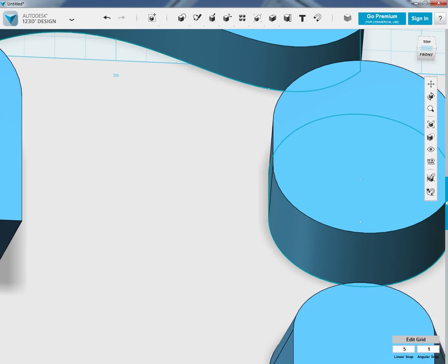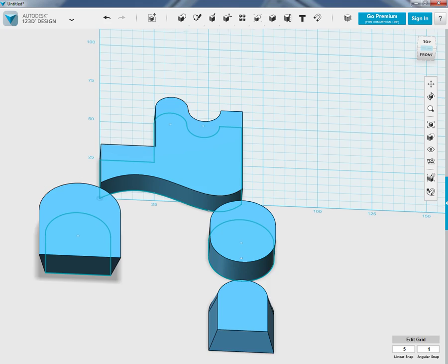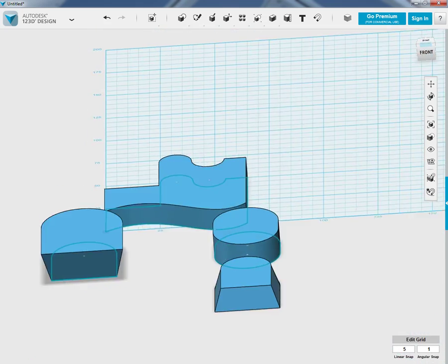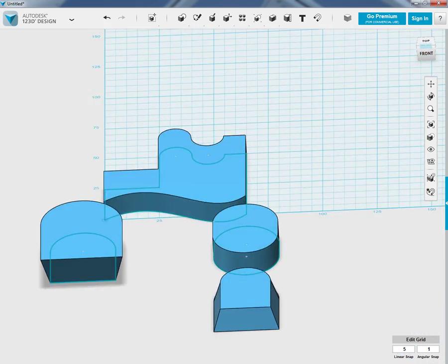That's quite nice. So then again, it's also not quite working with the standard 3D CAD package. When I put those fillets in, what it should have done in my mind is it should have added the fillets to this shape. So this shape that I'd already created should have been modified, and it hasn't.